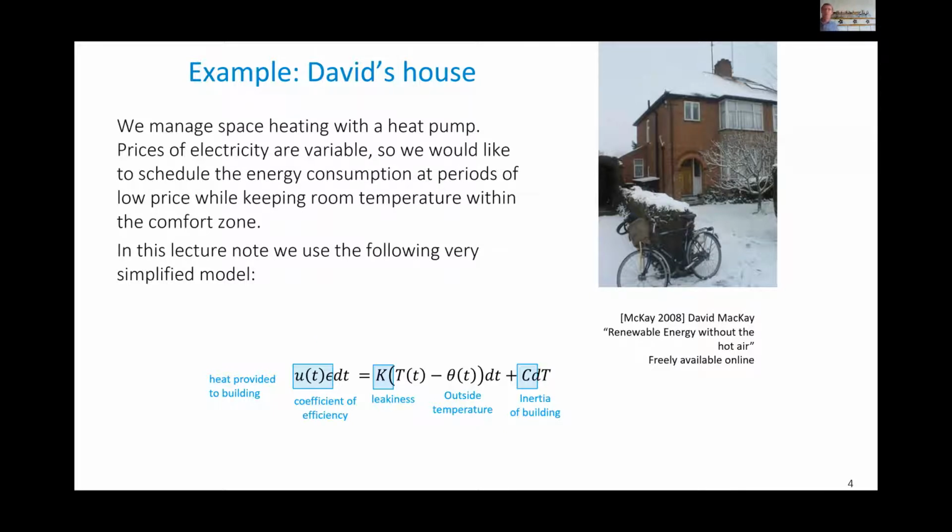It ignores two things. One, which is not very important and is often not completely disregarded, is the fact that the house is not a homogeneous system. There are multiple rooms, so the leakiness might be different for different rooms. Probably the rooms that are close to the roof leak more than those that are downstairs.